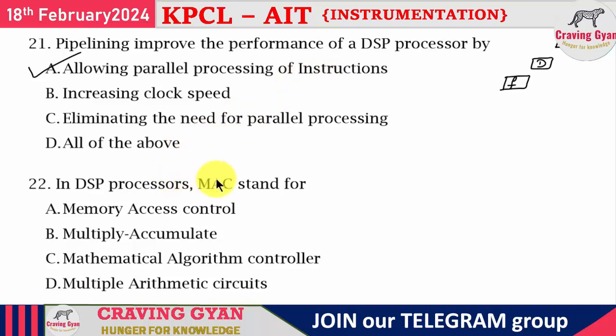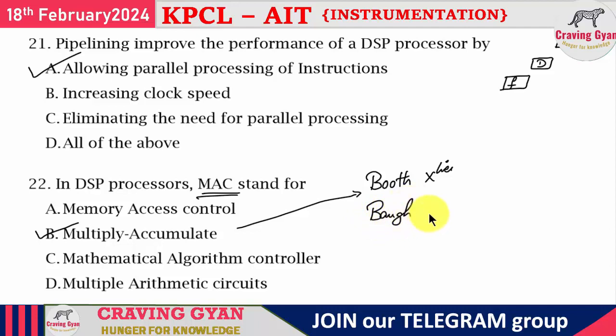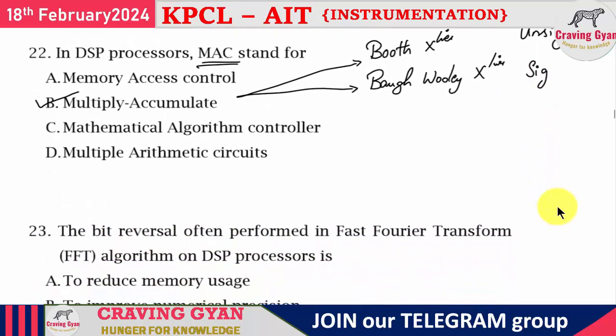22nd question, in the case of DSP processor, a MAC dedicated unit block will be there. So it is referred to as what? Multiply and accumulate unit. So here we are going to make use of signed and unsigned multiplication. One is the Booth multiplier, and the second one is the Baugh-Wooley multiplier. One is used for unsigned multiplication and the second one is used for signed multiplication. Option B is going to follow.